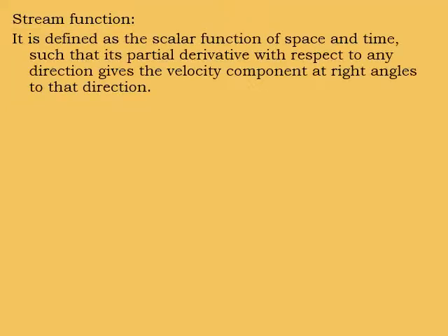Stream function. The stream function is defined as a scalar function of space and time such that its partial derivative with respect to any direction gives the velocity component at right angles to that direction.